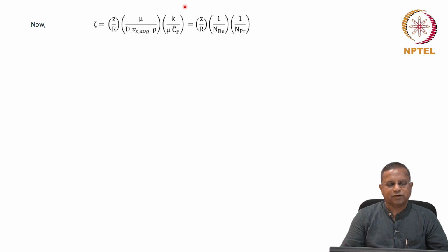Prandtl number is a very relevant non-dimensional number in heat transfer situations, heat transport situations, when you are looking at the transfer coefficient approach. Okay, very useful, widely used. So, k by mu rho Cp is nothing but the inverse of the Prandtl number. So, you can very clearly see that we have written it as a product of non-dimensional variables that we can easily understand.